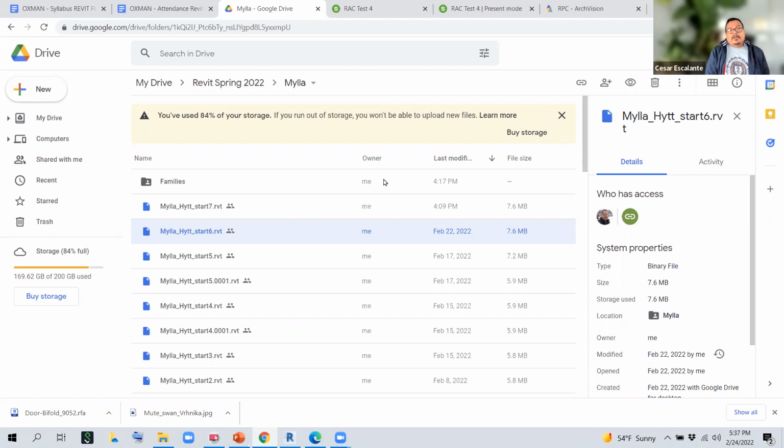If you're familiar with AutoCAD patterns, those are files with the extension PAT. Creating a pattern from scratch manually is super difficult, but it's very easy to find and search for patterns on the internet. I'm going to show you how we can import a custom pattern into Revit. And then we're going to create a camera, try to render, and finish that.